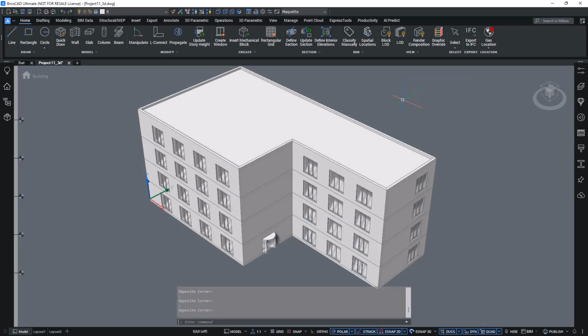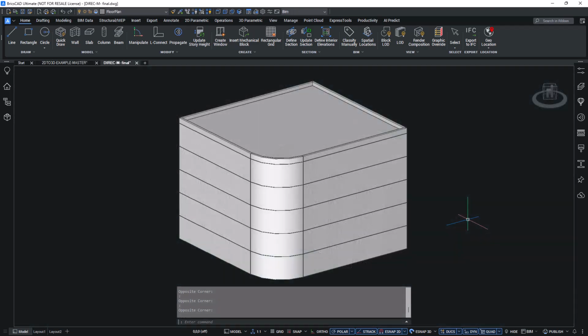Please keep in mind that to be able to insert library beam blocks in the top view mode, your beam model has to be classified. If your model only has simple geometry, like the one created in the Converting 2D Designs into 3D using Direct Modeling Tools lesson, you can still insert library blocks, even if the model is not classified yet.